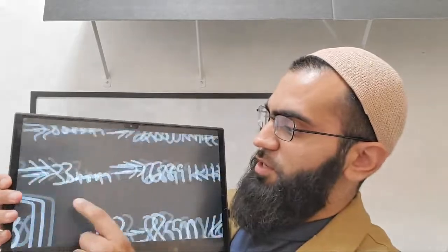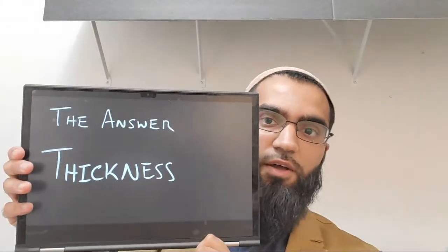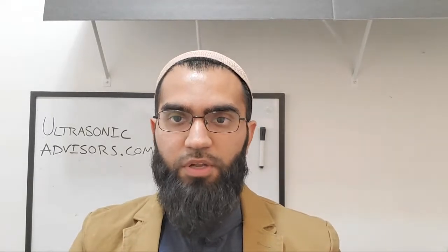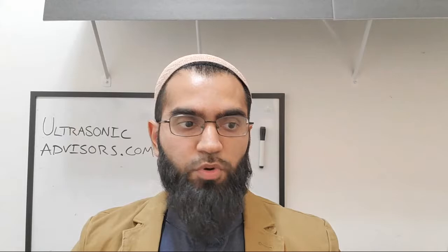So the answer was, well, okay, let's zoom back out. The answer was it's the thickness mode that is active, although it's not a perfectly behaving thickness mode, because the ratio is not appropriate: 3 millimeters thickness and 8 length, or 8 diameter. So it's not the best aspect ratio, but the mode shape is going to be more closely related to the thickness mode.